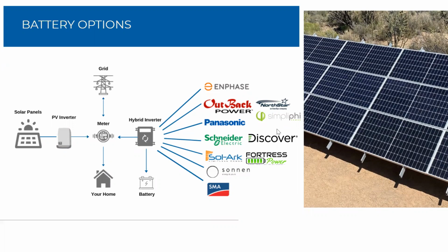So we have some kind of brand loyalty if you want closed loop communications, but you can have the Simplify Phi 3.8 kilowatt hour standard unit installed with any of the Skybox or the Radian or the XW Pro or the Solarc 12K. So we can really mix and match, if you will, any 48-volt battery with any 48-volt inverter.